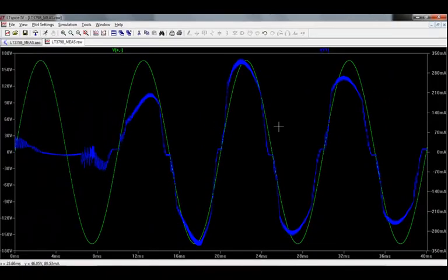Even though the waveform viewer shows us that the current and voltage are in phase, it does not provide us a method to calculate the actual power factor. To calculate the power factor, we're going to need to get the ratio of the real power to apparent power at the input voltage source V1. So let's go back to the schematic editor and take a look at some .measure statements that I've already included that do this calculation.